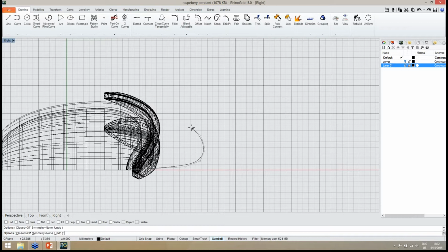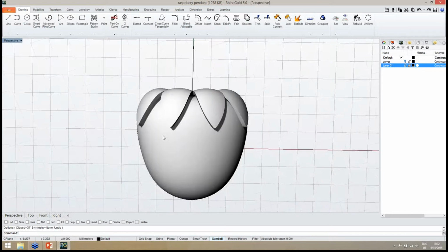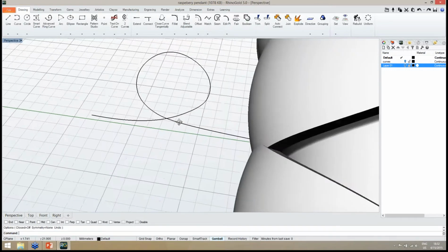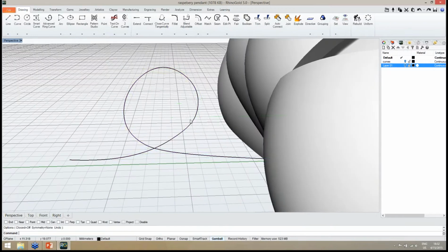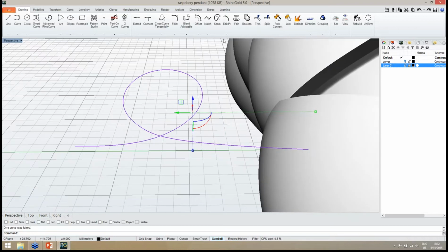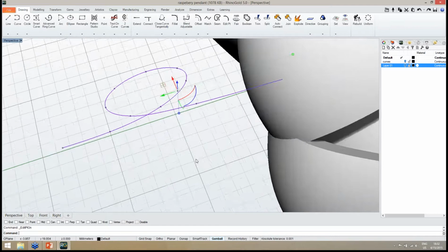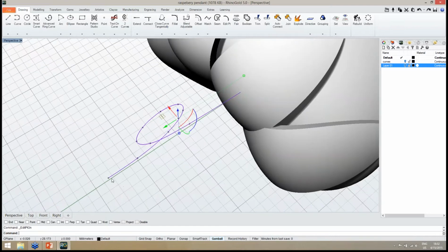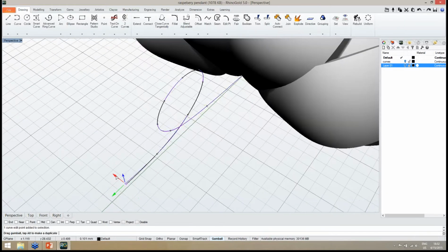So I'm going to make something like this. Okay, as you can see, it's exactly in the same position. So what I'm going to do now, it's first to smooth a little bit the curve with a fair tool. So I smooth, and now with the edit points I can adjust. For instance, I can start in here to move with the gimbal these points a little bit to the left side, so something like this.